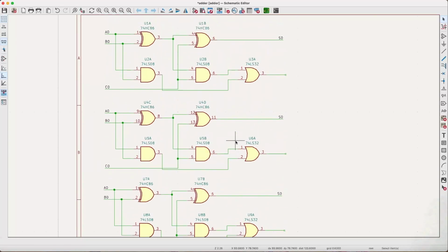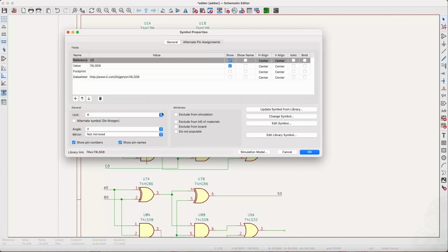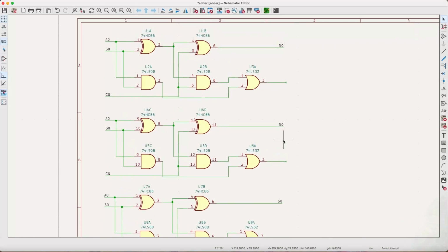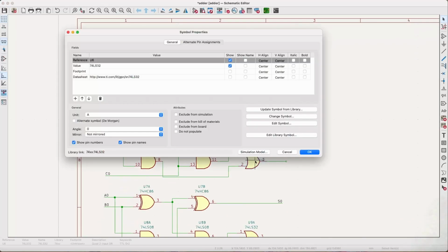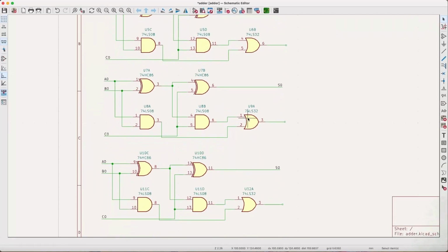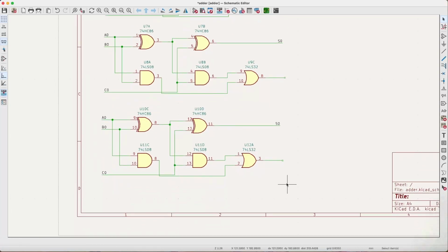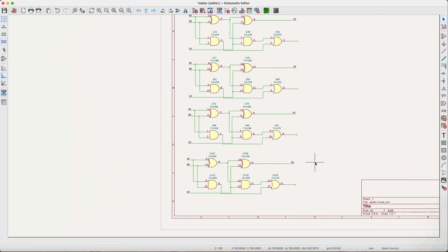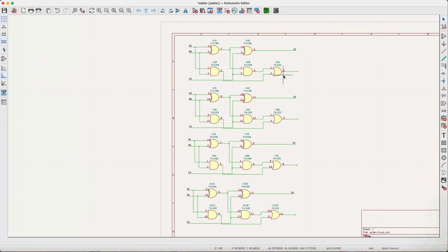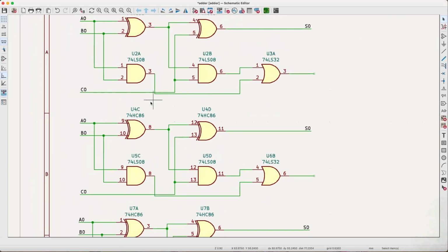And then we need to do the same thing for our AND gate. So we've got A, B, we want this to be C, and D. Finally, all of our OR gates are currently unit A. We'll make them all different, and then we'll just need a single chip on the output for our 4 OR gates. So this is everything we need for our 4 bits, but we need to feed the output of the carry to the carry in down here.